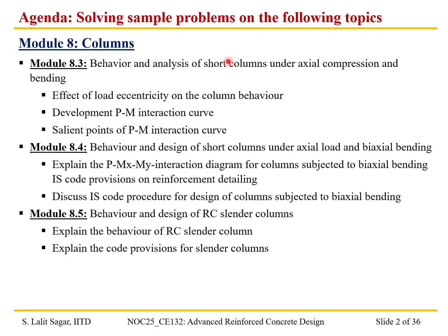Under module 8.3, we studied the effect of load eccentricity on the column behavior, because in modules 8.1 and 8.2, we essentially studied the behavior of columns under pure axial loads, right? So in this module, we considered the effect of the bending moment acting on the column, how that influences the stress distribution, and how we analyze and design the column accordingly.